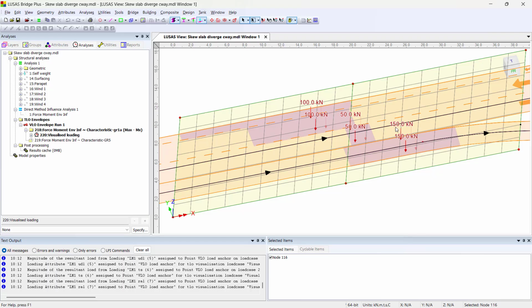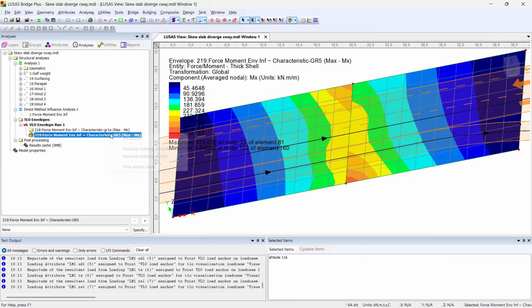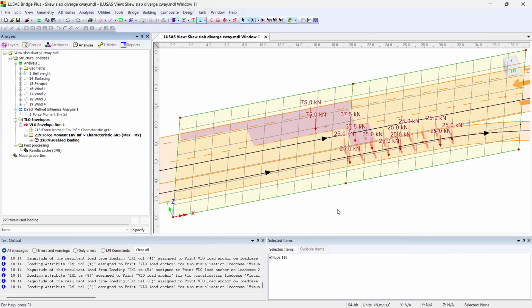So when we've got lane 1 with the heaviest vehicle here, even though we've got a separate carriageway over here, we're getting lane 2 and lane 3. We're not getting another lane 1. We could also look at the LM3 results, where we can see that the heavy vehicle has been placed in the divergent lane.